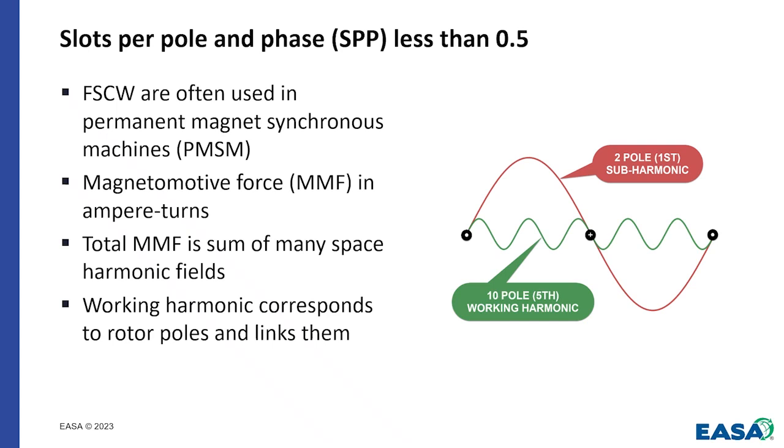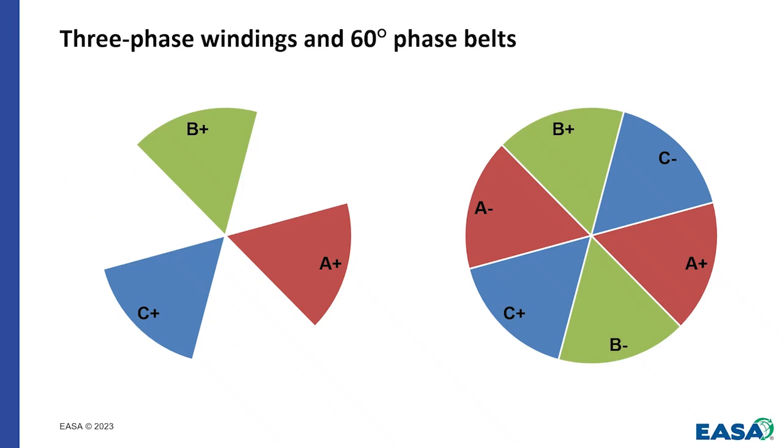So the way we typically lay out the three-phase windings, and we're going to talk about this in terms of a two-pole machine, the way we typically lay these out is what we call 60 degree phase belts. That's our typical two-layer lap winding. And for any three-phase source, we want a winding that has 3 individual windings, one per phase, separated electrically by 120 degrees, and in time by 120 degrees as well for the supply.